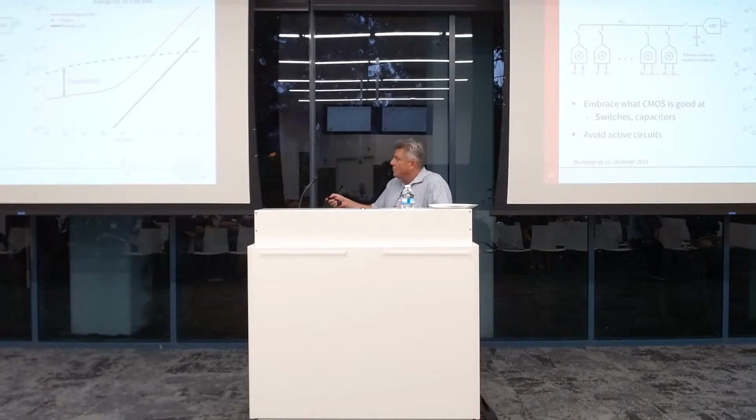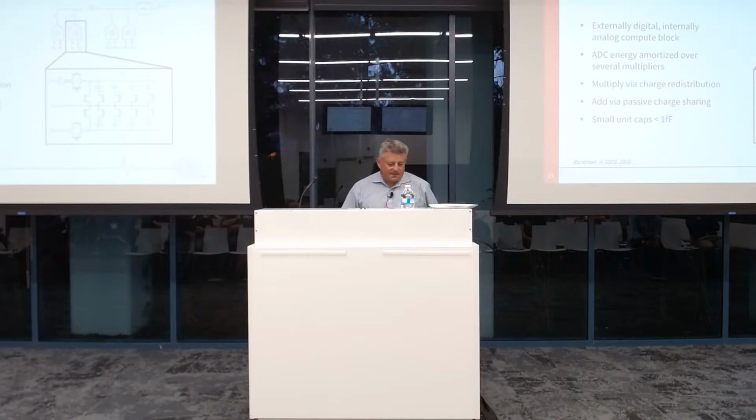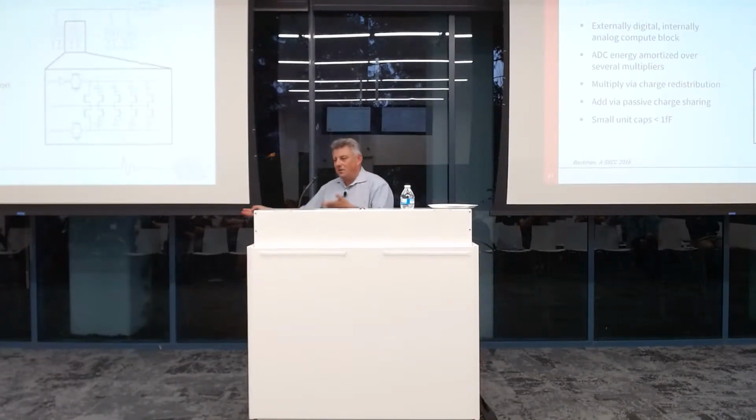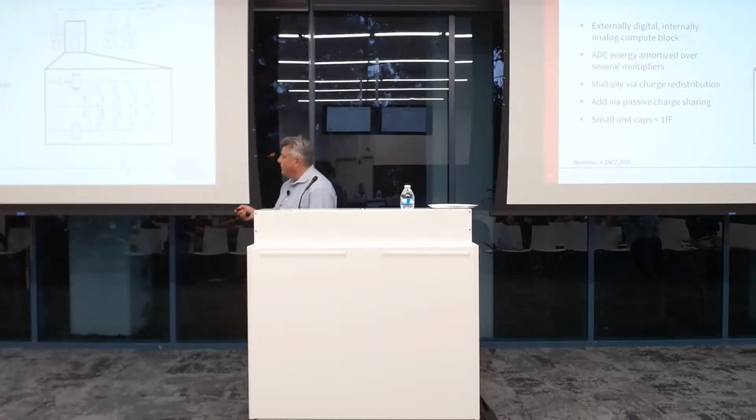So it turned out we saw this and said, hey, there's 10x to be had. Let's build something and do that. We worked very hard. We knew people want to do MAC operations, multiply-add. So can we really show this 10x? We set out to come up with an architecture, and we built this with very small transistors in an advanced process, 1 femtofarad caps, and so on.